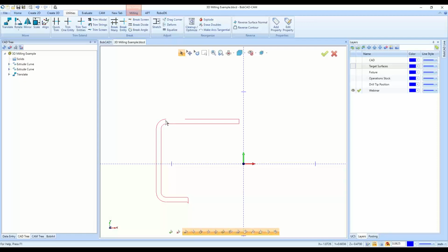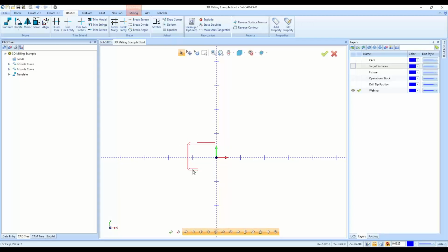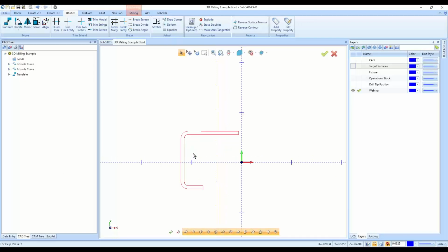It's where you have an issue there because you haven't closed off the geometry for selecting the geometry of the actual pocket. The software doesn't understand you want to pocket this, but everything outside of it also is everything. So anyway, that is why the chain selection is very, very useful. It will also tell you any areas that haven't been closed up for your geometry yet.